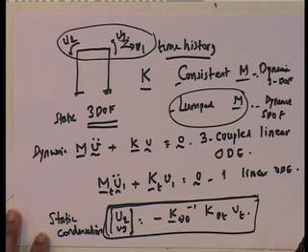The advantage of the consistent mass formulation is that whatever frequencies you get are upper bounds. If you solve the free vibration equation using the lumped mass formulation, you cannot say that the frequencies you get are upper bounds. They are close to them.